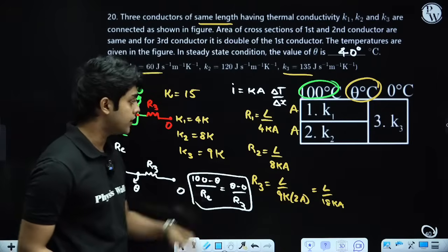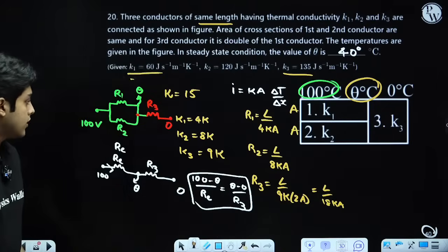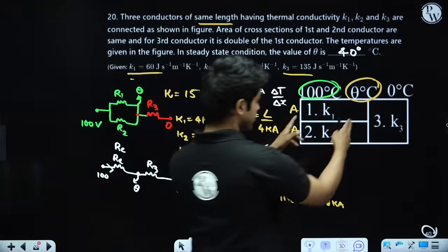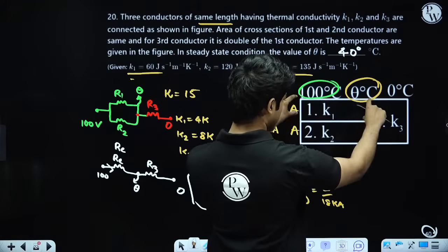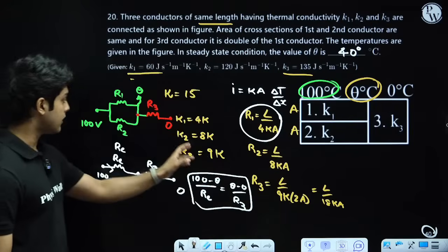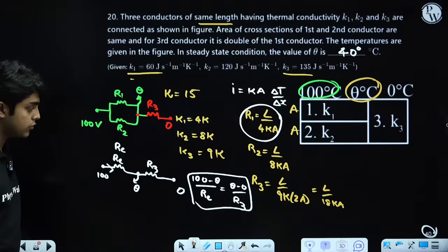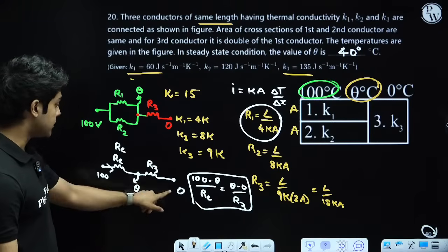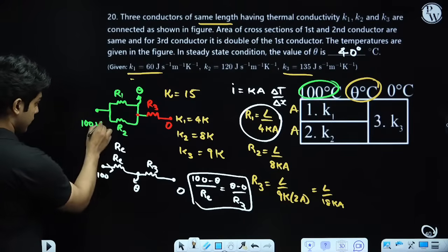I mean that's what we did, but the main idea is we have to convert these into thermal resistance L by Ka, and then once we get that, we can use Ohm's law to find it. Instead of temperatures, we can convert that into potentials, right?